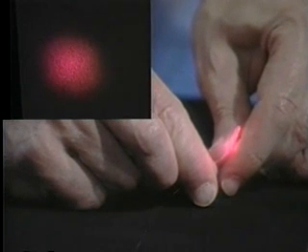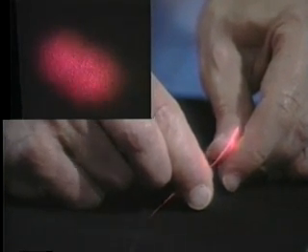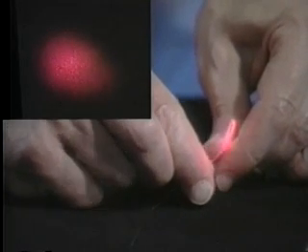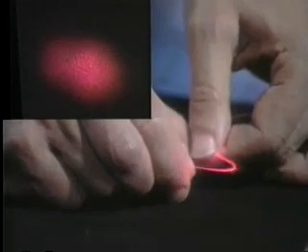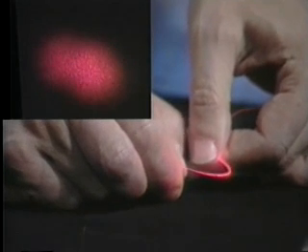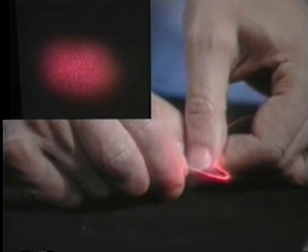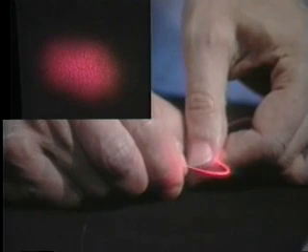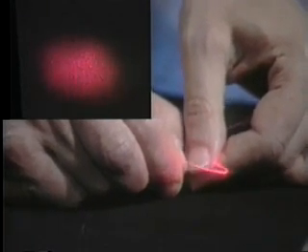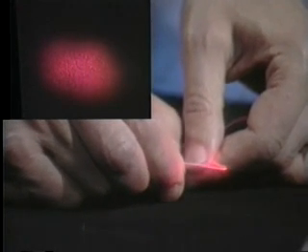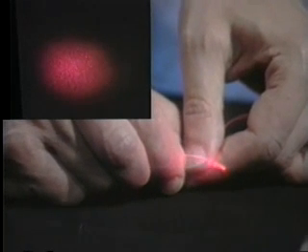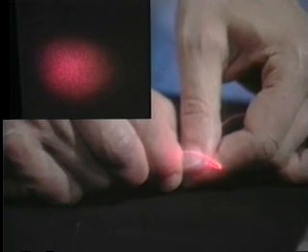So here we have single mode propagation, and here we have multimode, or a mixture of multimodes, that are propagating in the fiber. Again, you can see that there's a lot of light that gets kicked out of the fiber. You can see the bend absolutely glows. In fact, this bending effect on the transmission of light in a fiber can be used as a sensor. A sensor of pressure, sensor of stress, bends, and what have you.